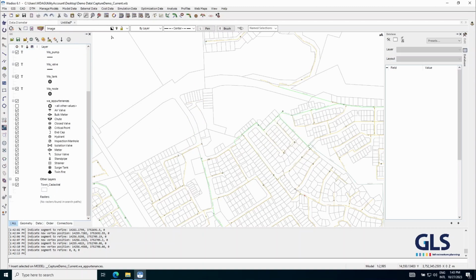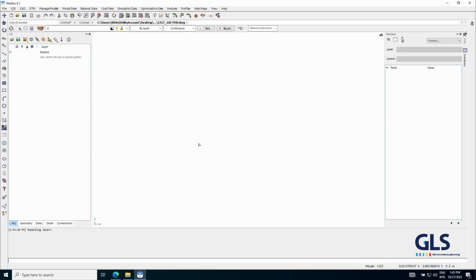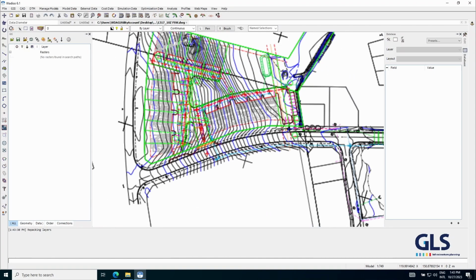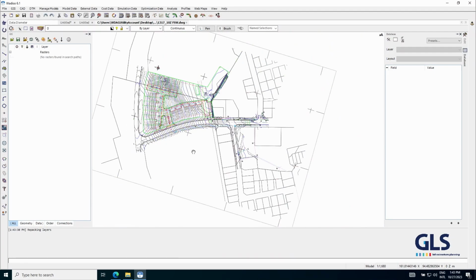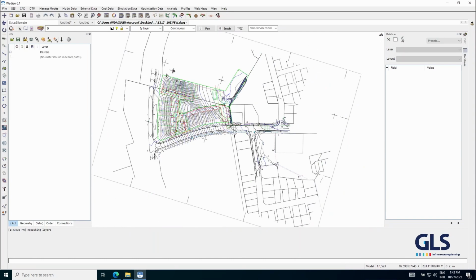And the second item that we're going to look at is if you received a DWG drawing. So on a new drawing, I'm going to open the same drawing that was received in DWG format. Then, just making sure after loading that I zoom to the current selection. Again, you can see it's the same orientation as we had for the PDF in terms of the north arrow pointing. So we need to do the fixed coordinates exactly the same.